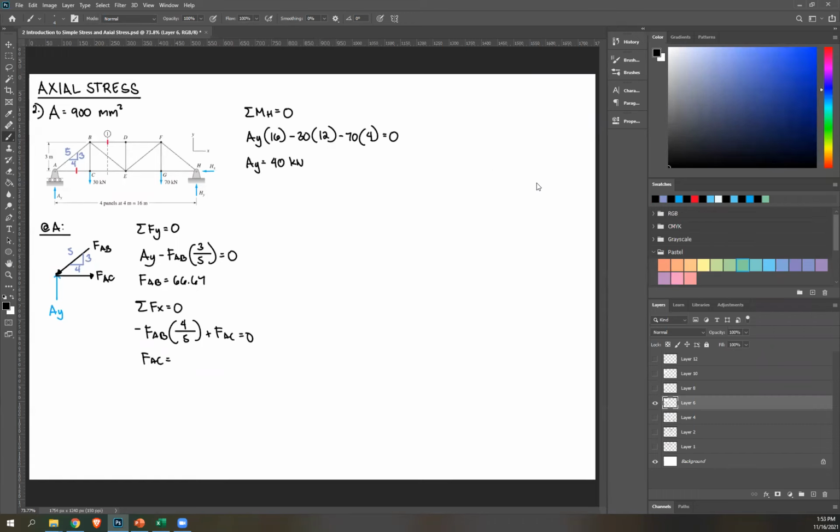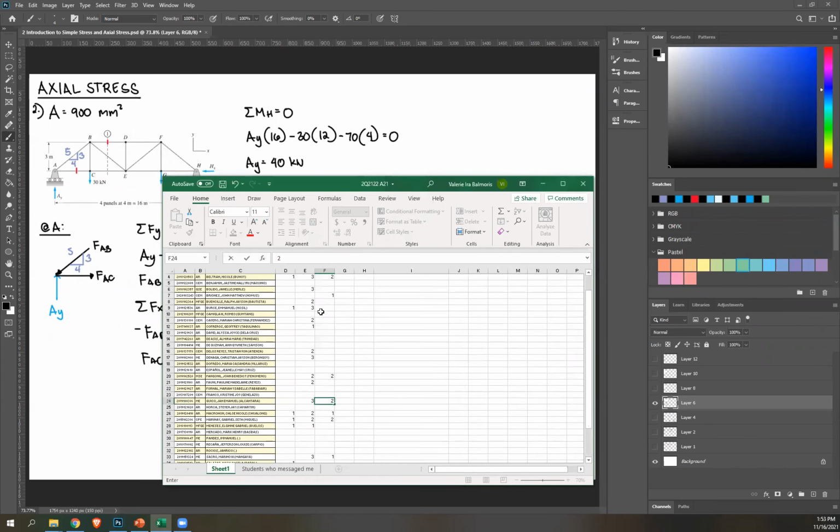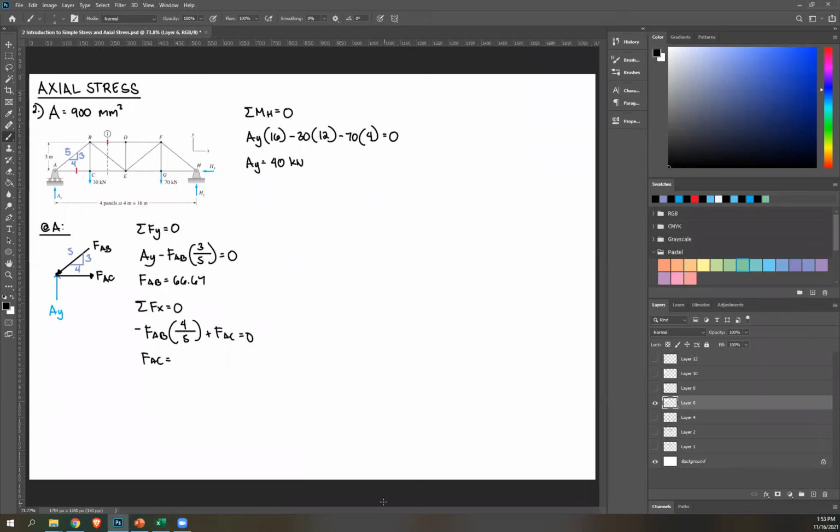Correct? 53.33. Okay. Now take note. You should have stored this value when using it here so that you get the actual result, which is 53.33, not 34. Okay, and then positive, therefore correct assumption. Unit is kilonewton. And then it's away from your joint, so that's tension.